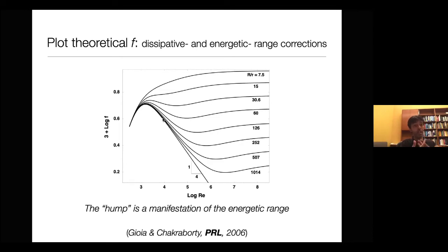In other words, using the whole form of the spectrum and using rather simple arguments, with lots of simplifications, admittedly, that effectively capture the notion that turbulent shear stress comes from the transfer of momentum due to turbulent eddies, we can connect turbulent friction with the energy spectrum. And this is the prediction from it. You get the hump, you get the bellies, you get these scalings, which were empirical until this point, of Blasius, the smooth scaling, and Strickler, the rough scaling, where the exponents of these scalings are tied to the 5/3 exponent of the Kolmogorov spectrum.